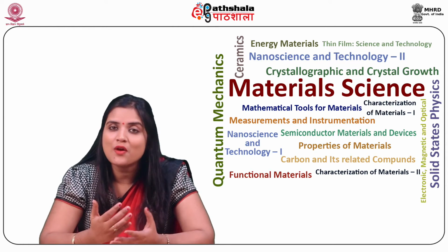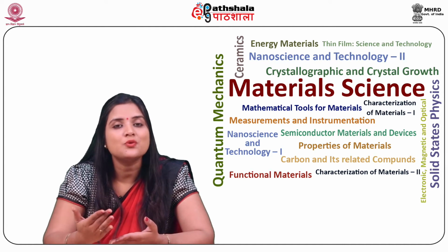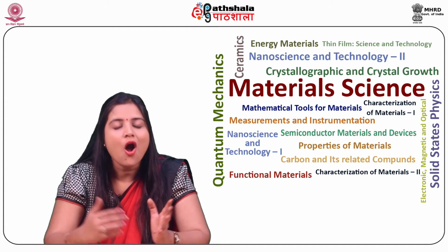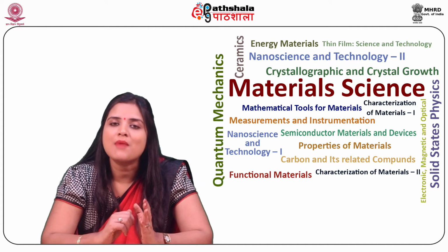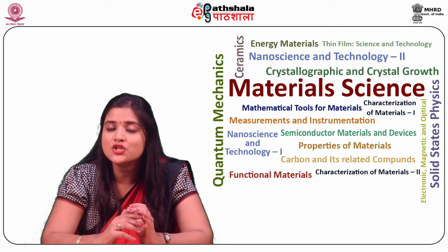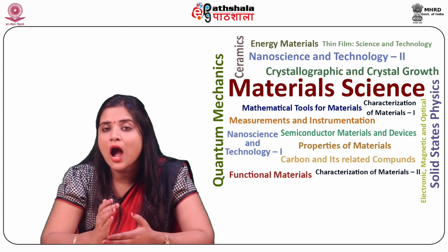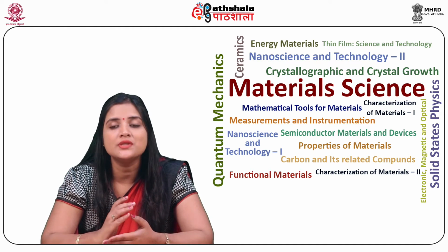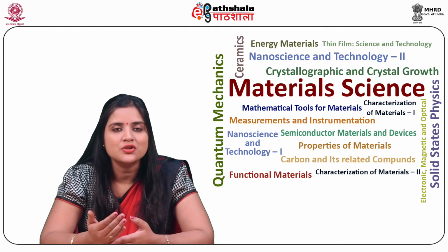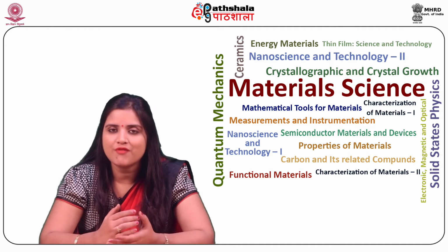The name is derived from the fact that the output voltage is equal in magnitude and in phase with the input signal. That is, the output signal tracks or follows the input signal in magnitude and phase. In order to obtain the voltage follower circuit for unity gain, we can see from equation 5 that Rf should be equal to 0, that is short circuit, and R1 should be infinite, which means open circuit, as shown in the circuit in figure 5.